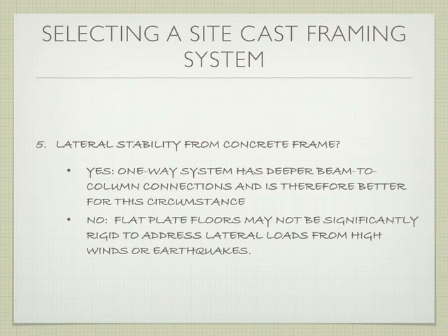We talked at the beginning of class today about if you're in one of the newer houses where they built the slab and post-tension the slab, even though it's a slab on grade, they put those post-tension tendons in, and they tighten it up, and they put those stamps on the floor that say don't drill into this slab. If you want to drill into the slab because you want to, say, convert a half bath into a full bath and add a shower, you can't drill into that slab to bring in your plumbing or to put in your waste, because it has those post-tension cables in it, and you could damage the overall slab.